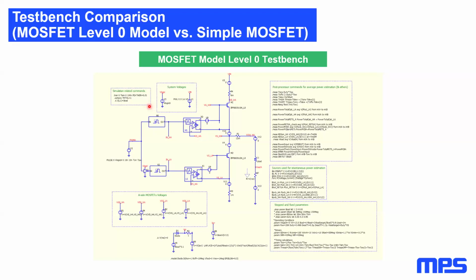When doing manual calculations, or when you have a simulation bench like this one, instead of having a constant load, one can simply emulate the current levels, the waveforms themselves, and most importantly, the power dissipation has to be integrated over an electrical rotation period, let's call it like that, which will be the period of the current waveform.